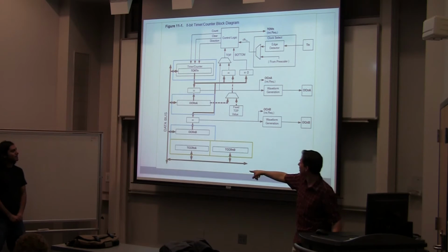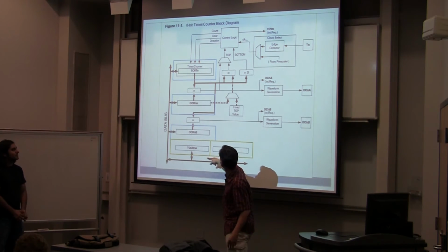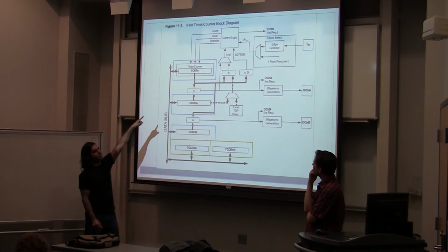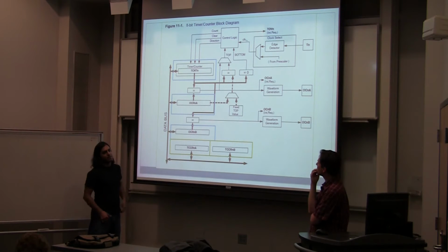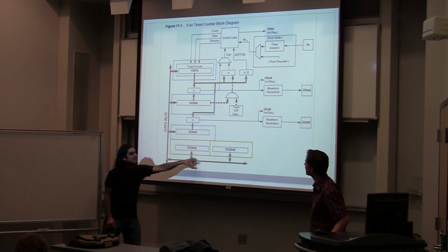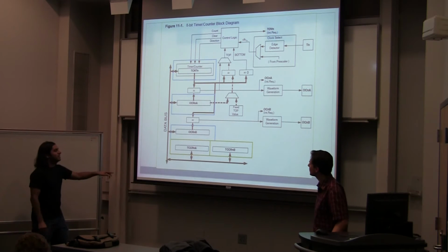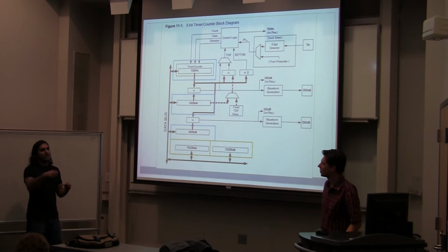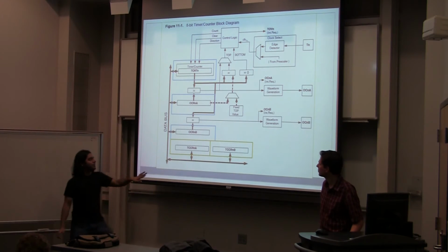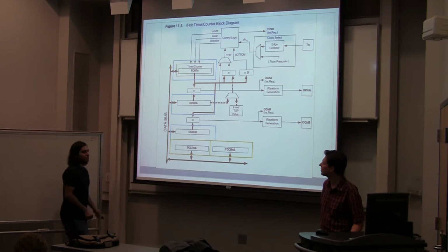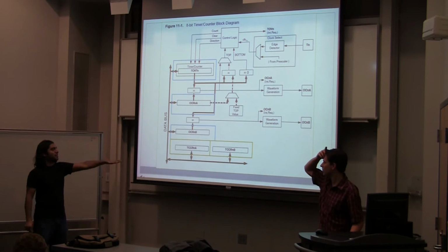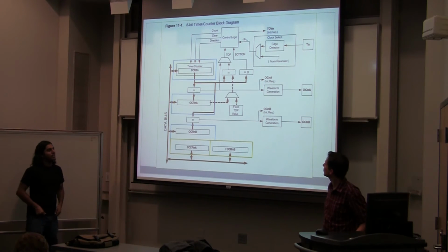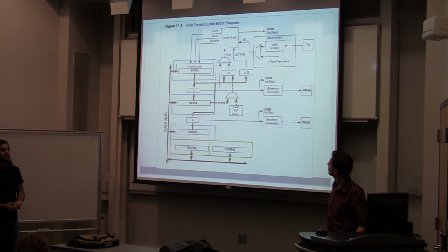And then there's the timer counter registers, which I'm trying to remember now. They set what this thing gets set or reset to, depending on stuff. Basically, depending on the mode of the timer, these set what TCNT will be on certain time events. So for example, if you're counting down, when you get to 0, I want to load it back up with the values in this register. Or when I reach 256, I want to start not from 0, but from 20 or something. And so that lets you adjust the timing of the things that you're doing.